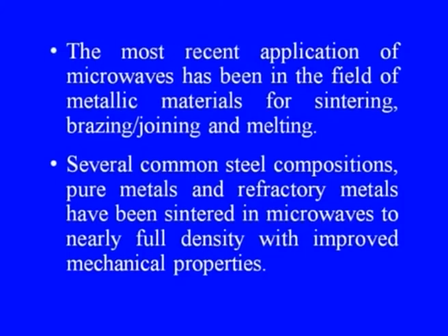The most recent application of microwaves has been in the field of metallic materials for sintering, brazing, joining, melting and cladding and so on. Several common steel compositions, pure metals and refractory metals have also been sintered in microwaves to nearly full density with improved mechanical properties.